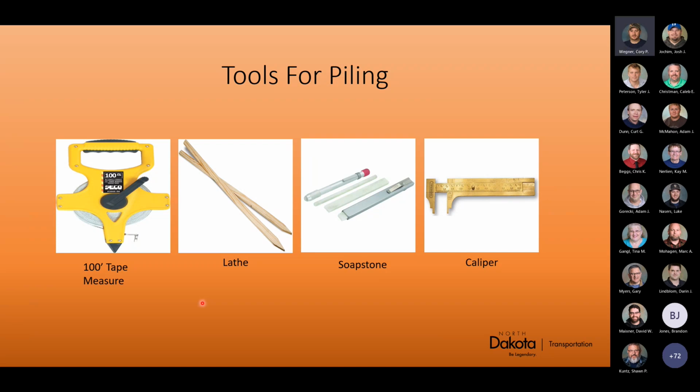And typically, when we drive piling, we use 2 people to make sure that we've reached bearing. 1 marking, 1 measuring. Just get that second set of eyes. And then a caliper. For quite a few years, I used the tape measure to measure your marks in 10 blows, and it's pretty hard to get a reading on what that penetration was.